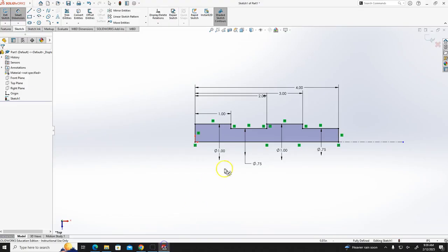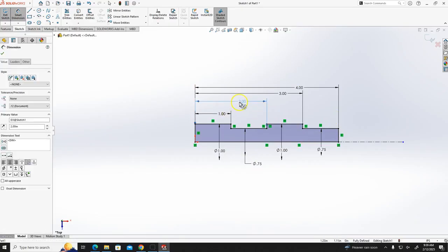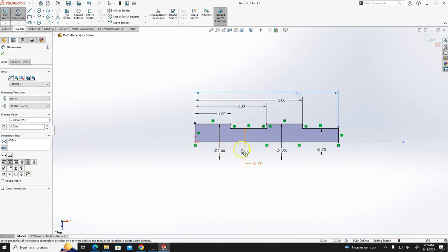First thing, we are going to create a shaft, and for that shaft this particular sketch will be drawn, and that will be revolved by using the revolve boss base command. Make sure that all the dimensions are given and you use revolve boss base. Now you can use the revolve boss base. So everybody is fine with this? Everybody was able to do up to this?